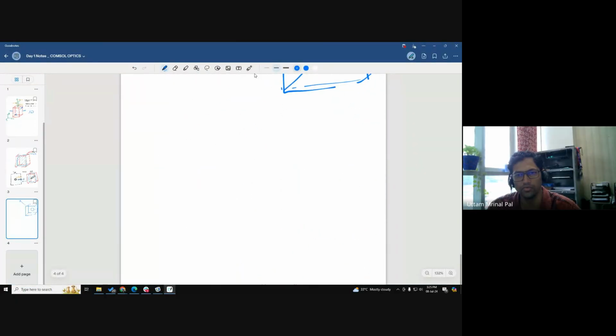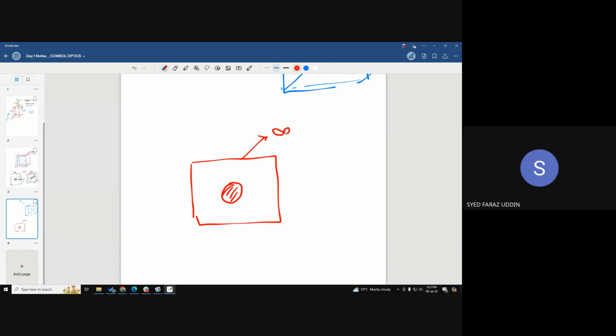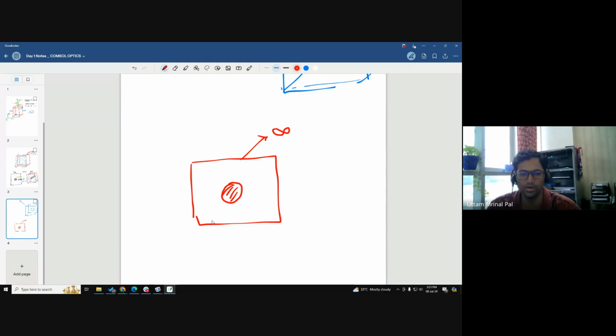What is happening in COMSOL is that, if you model this structure over here and then say I extend towards the inside, it's modeling towards infinity. So it doesn't matter whether it extends toward any side. Ideally, it assumes that it is the cross section of an infinite structure.